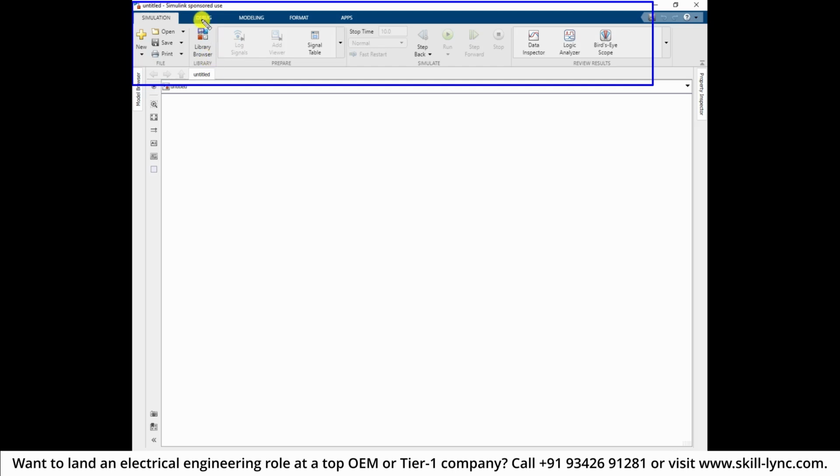And there are many options like debug, modeling, format, and apps. Apart from that, here you have an important window with the buttons related to simulating your model. So once your simulation is built over here in the blank area, you can configure run, stop, and step forward or step back. And there are other options of logic analyzer, data inspector, and other things as well.